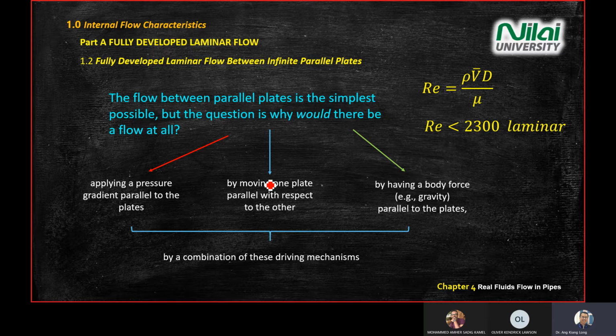All right. So the first one, the one that you see on the screen here, remember the Reynolds number, which is the first equation that you learned today. Second one, there's another equation, which is the L over D equation. And then the magic number 2300 that defines the flow regime. At 2300 and less, you become laminar flow. And we love laminar flow, right? We love laminar flow.